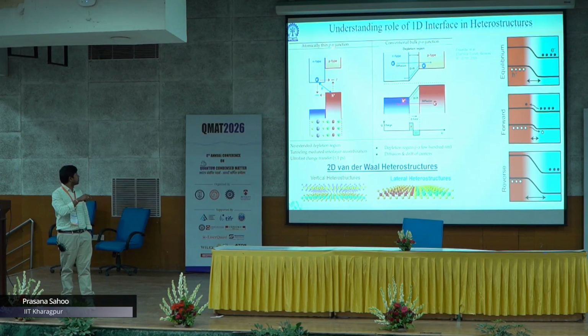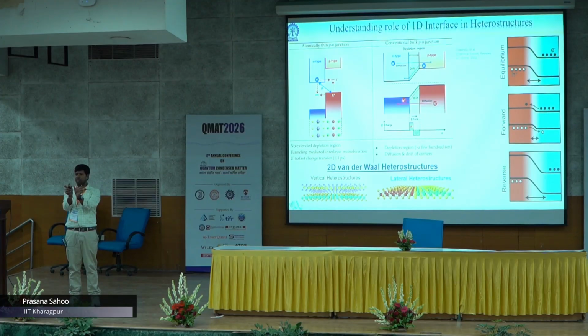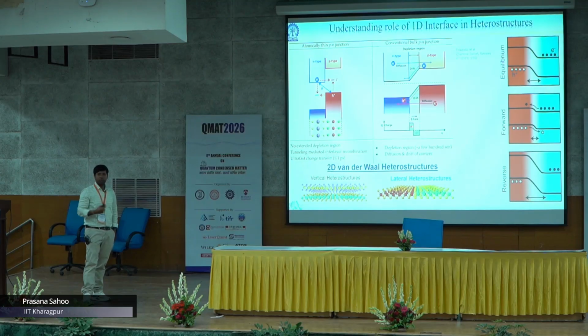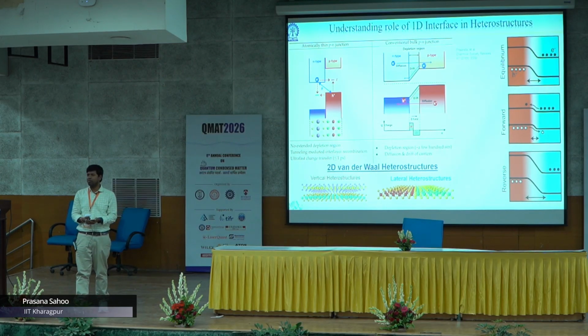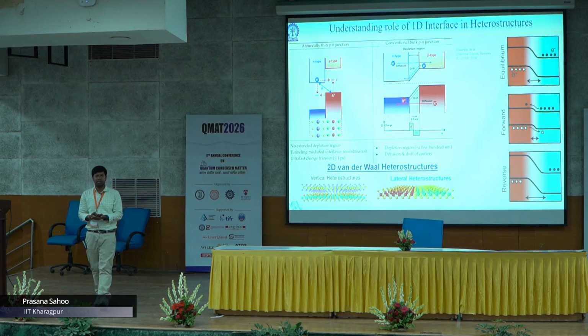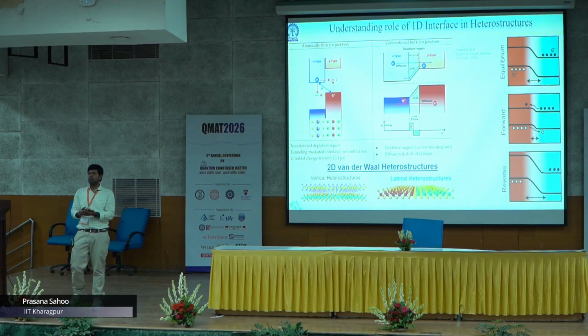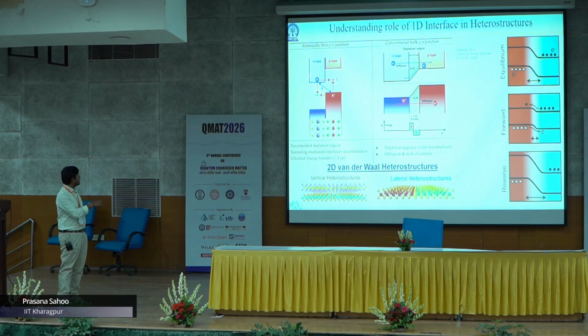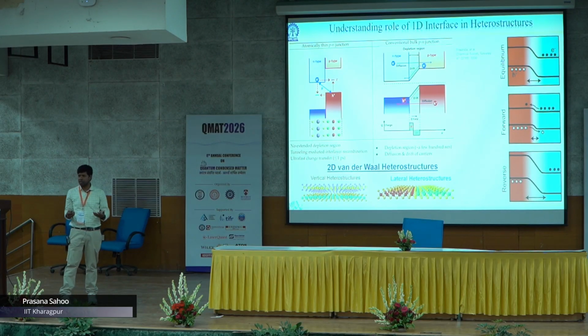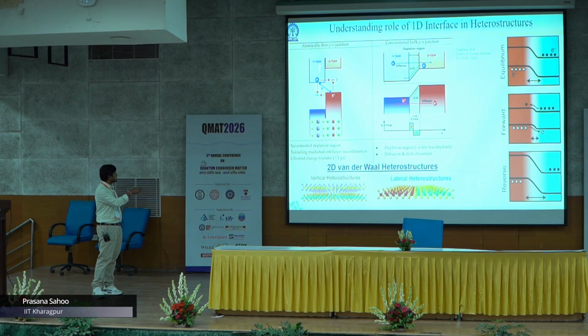So we all talk about PN junctions. In a bulk PN junction, when P and N type semiconductors are sandwiched, there is a depletion region present, which is several hundreds of nanometers. How about 2D materials? They are already in the quantum limit, already in the 1 nanometer limit. There is no effective carrier diffusion. Carriers are already confined to individual domains. Is there indeed any depletion region? So as per the previous work, when a PN junction is stacked from 2D materials, carriers can recombine in a tunneling-mediated process, because there is no drift or diffusion type process, because these are quantum layers.